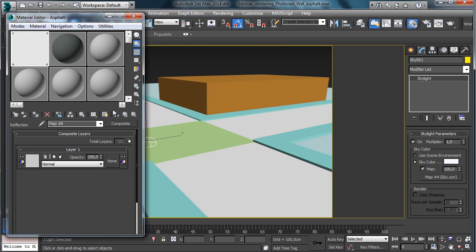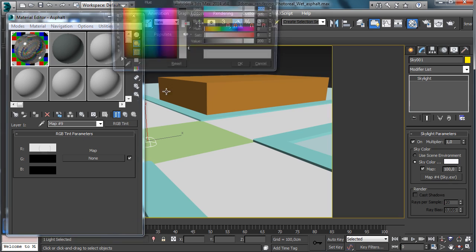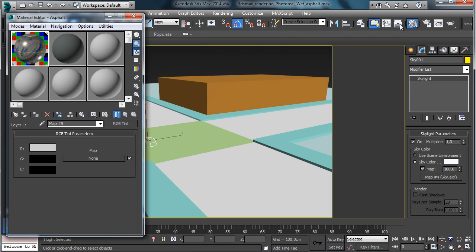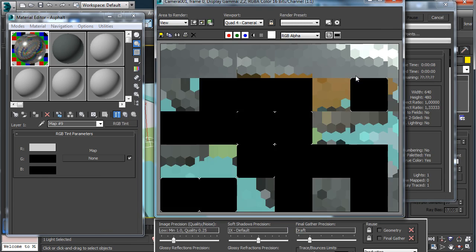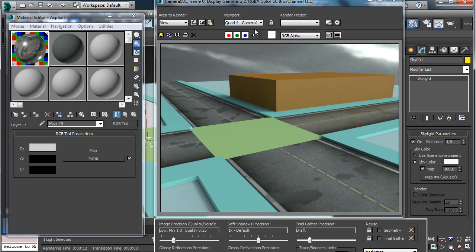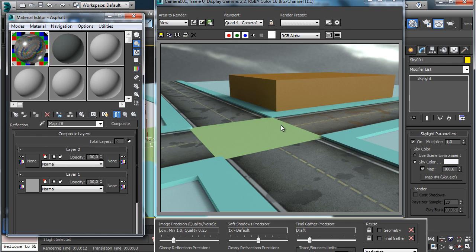So if we like to change the level of glossiness, we have just to play with this one, and you see that we have still less or more glossy reflection. Let's see what happened with this parameter. It seems not bad as reflection level, glossiness level. So let's go to have a control to say what do we have where we have the puddles. So we can go inside the color, copy this map with the right mouse button, and in the glossiness we can paste,